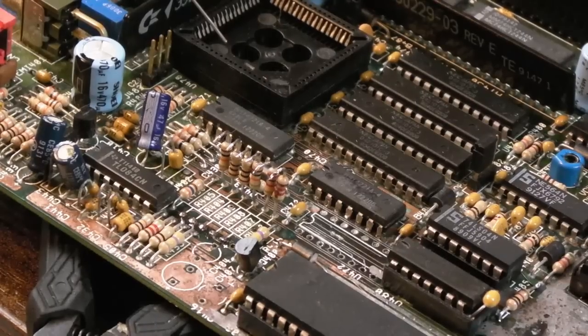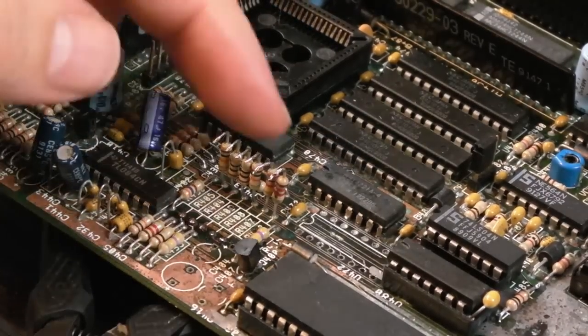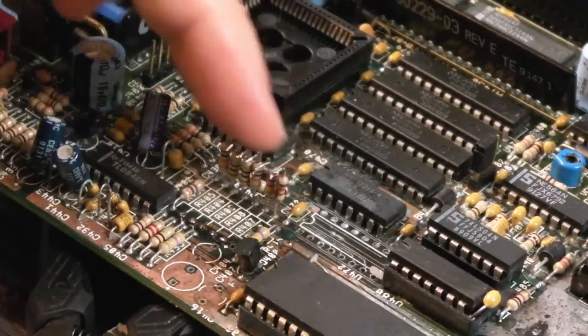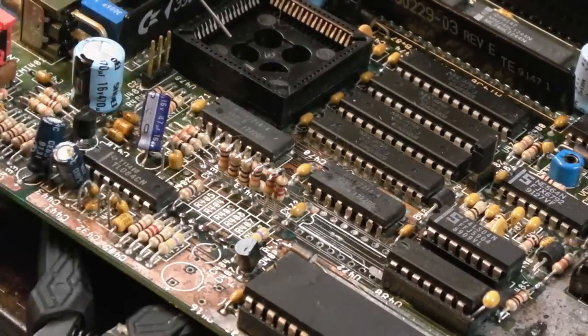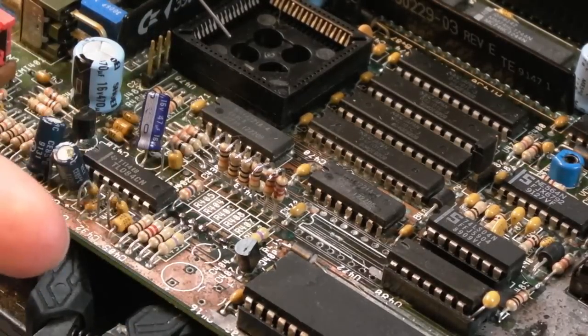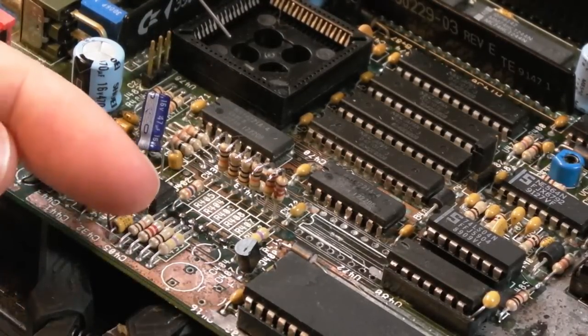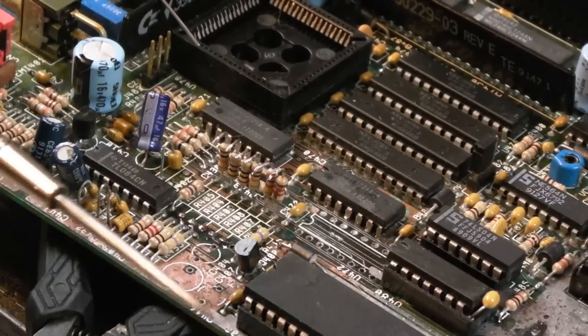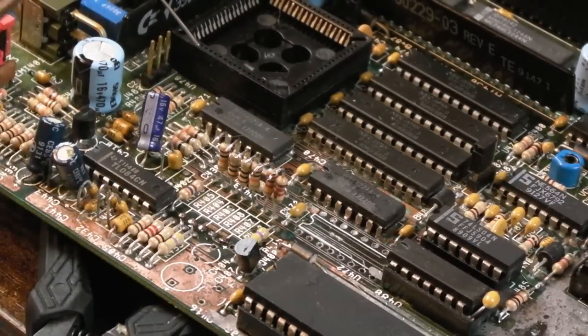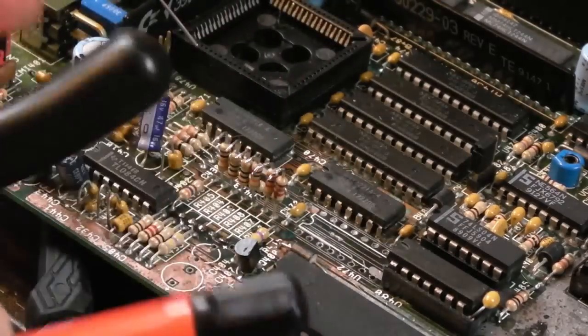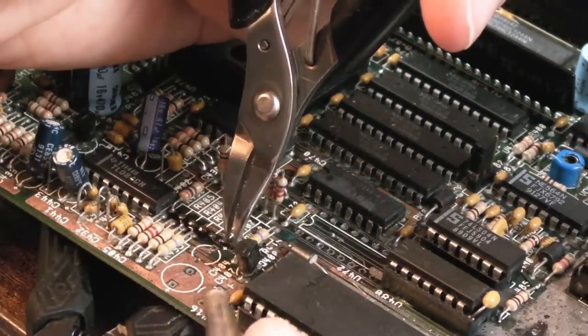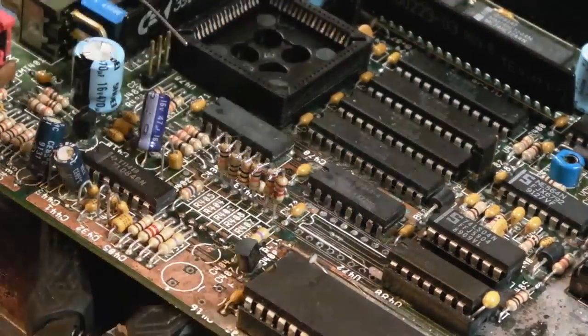And if you're anything like me, you want a quick fix to an area where the components look alright, the component legs are all cleaned up, they look alright even on the underside, but there are some vias here. Just straighten the pins on the underside, which is what I did first. Heat, and just use my pointy tool here to bend them out so they're straight, and then heat from the top side here, and use my fine nose pliers to grip the pin as you heat and just pull out, just lift them up.